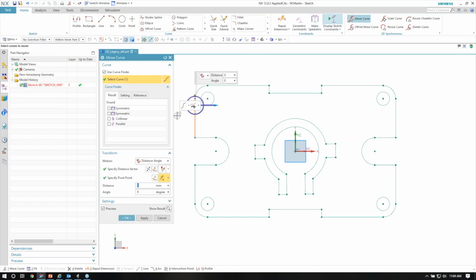Pick a move curve, and with synchronous tools we get this finder, and this one is a curve finder. So we can see symmetry left, right, and top, bottom. So I can see how it's picking the curve geometry up. And the next piece of geometry that I pick also brings up my curve finder again. So it sees, again, symmetry left, right, and top, bottom. So if I also pick up, say, concentric, it's picking up one of them, but only picked up one. So I'm going to leave that behind right now and then try to pick up that circle.